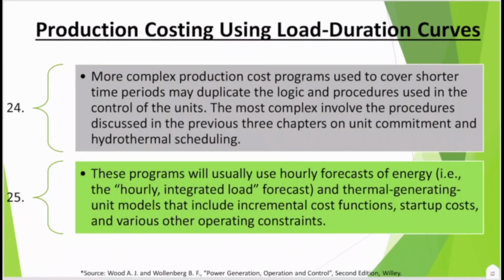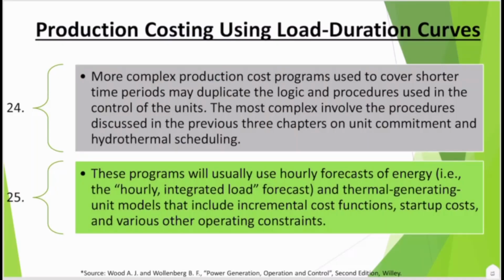The most complex involve the procedures discussed in the previous three chapters on unit commitment and hydrothermal scheduling. These programs will usually use hourly forecasts of energy, that is, hourly integrated load forecasts, and thermal generating unit models that include incremental cost functions, startup cost, shutdown cost, and various other operating constraints.